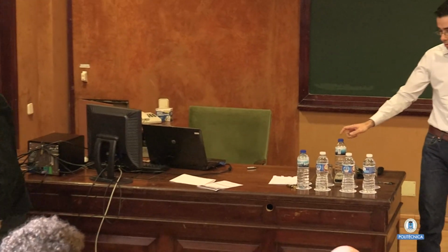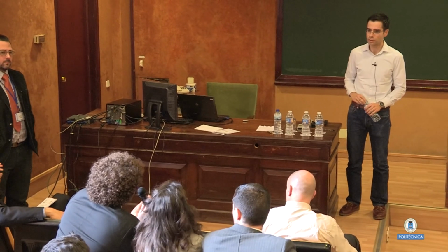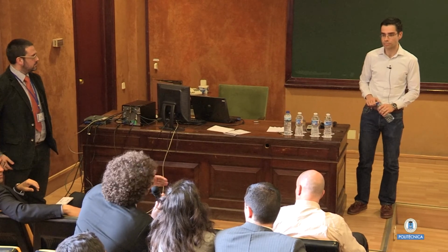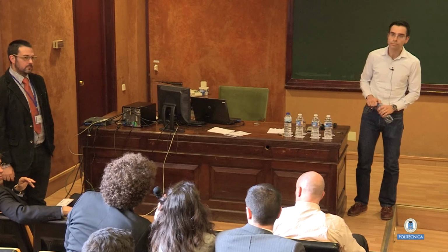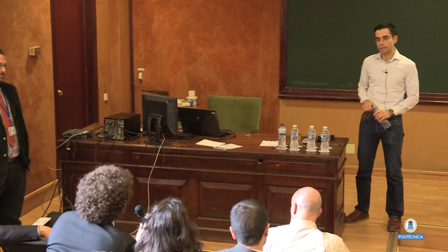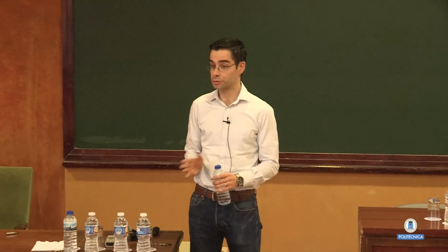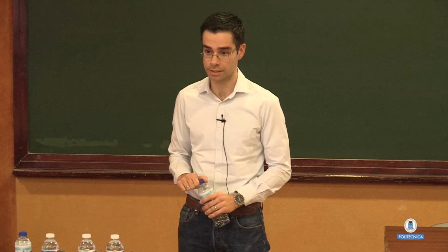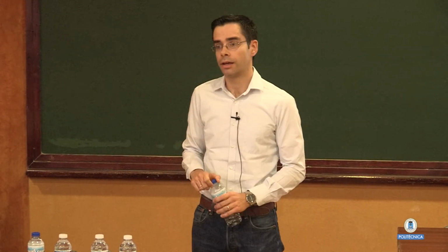Vladimir Šiković from UPM. I wanted to ask, how close can you put resonances of the traps, and how does that affect the efficiency, since if you have 10 traps, for instance, you're going to have a really wide range of operation of your converter. And how will that affect the losses, since I'm assuming that you're optimizing the efficiency as well? Right now, what we are saying is, if you have a converter, it's going to have a higher efficiency than a MOSFET and a resistor, but we haven't measured the efficiency. It's true, but we guess that the efficiency is not going to be very bad.